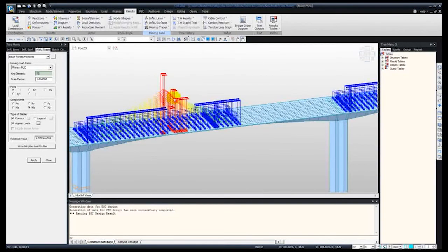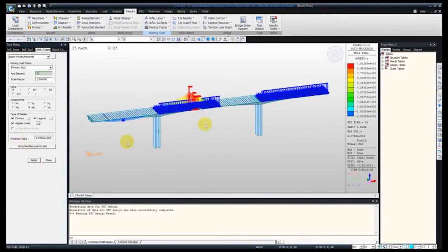Also the influence lines, the tandem loads and the UDLs are displayed. Let me show the legend as well. So here you can see the maximum value for the major bending moment, and on the right hand side you can see the influence lines and also the unit and other information about the particular point. This can be turned into static load case, and the coexisting forces can be checked for this.